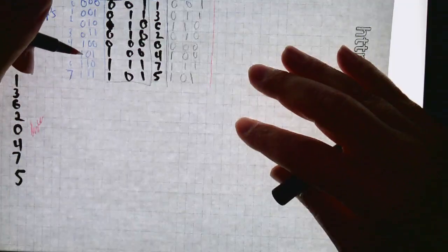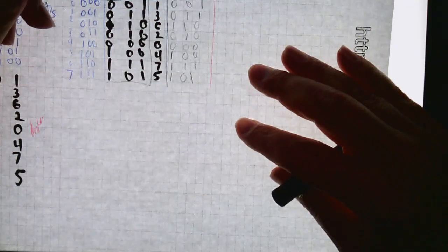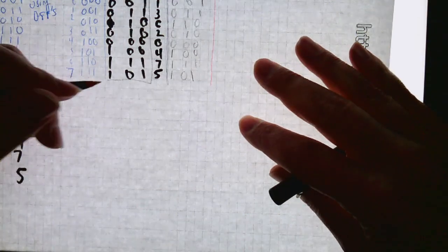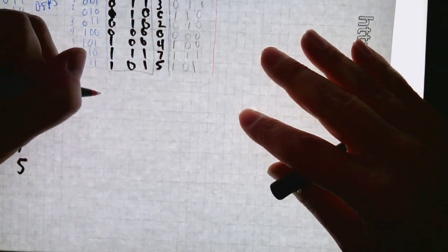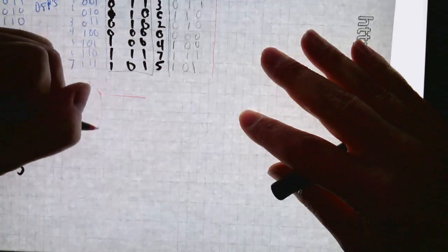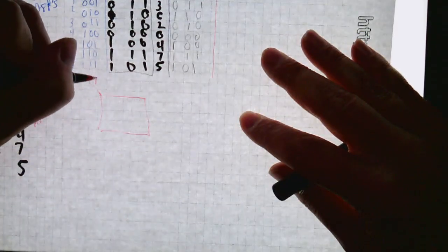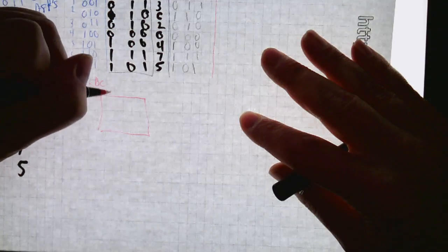So now, I guess it's time to start to think about how we're going to create a minimum sum of products form for this particular system, right? And we're supposed to do it with D flip-flops, it says. So one thing I can do is I can put out a K-map. Boy, this is not looking nice. B, C, and A.